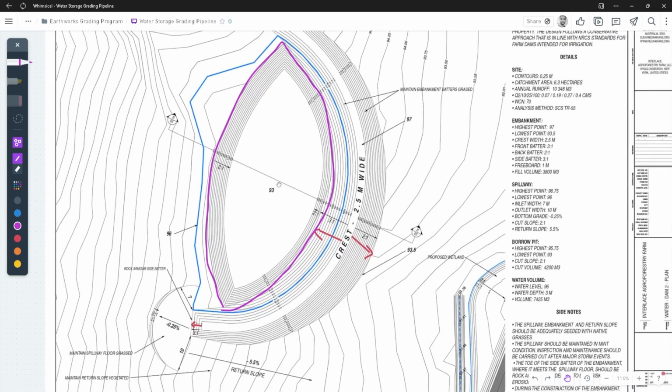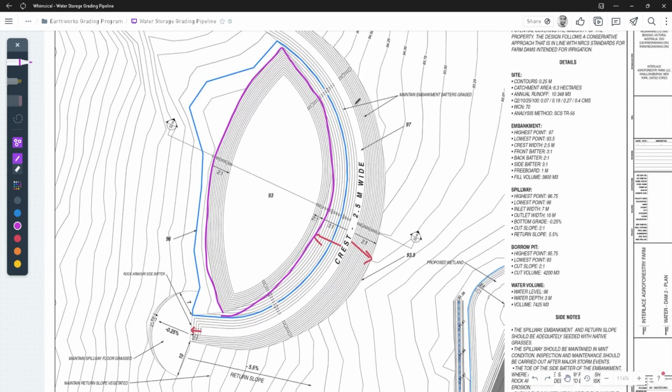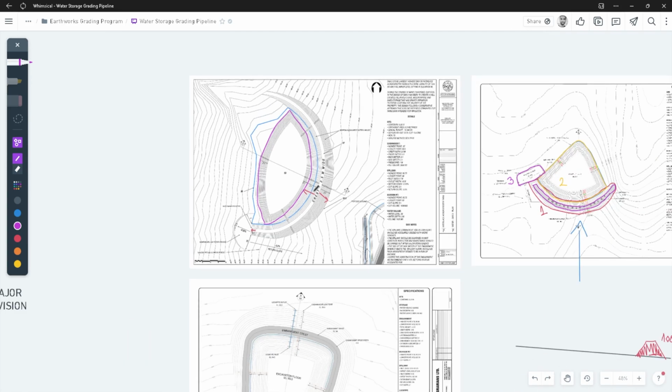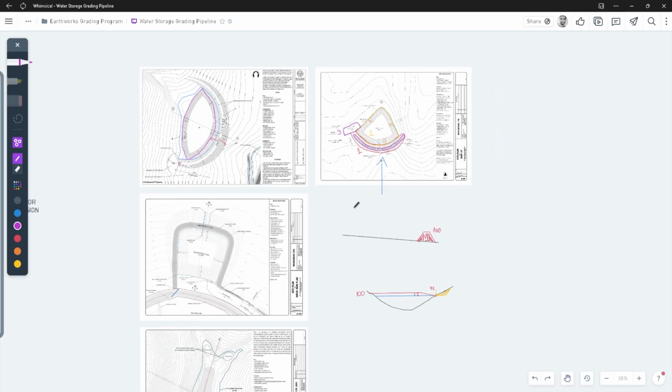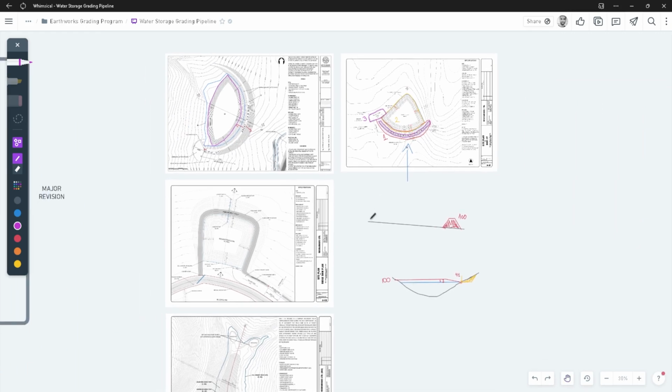Now, another option could be that just the embankment has to be either reduced or increased in order to either minimize the required material or to utilize material that is otherwise too much. So again, you can see how grading becomes very valuable, because it can save tens of thousands of dollars of work that is otherwise going to be either done for no reason, or it may end up being a disaster.